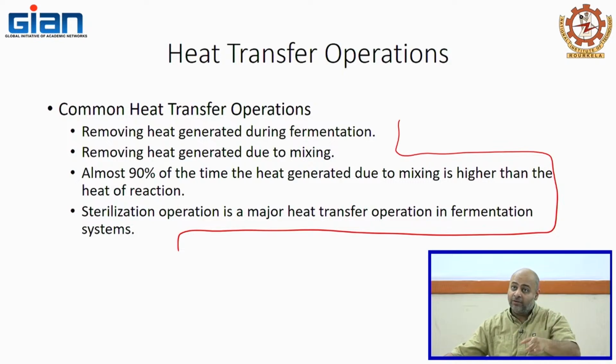Then again, it will depend on the fluid properties, the viscosity. You have to look into the table and get the values at a specific temperature: what's the viscosity of the medium, the density of the medium, and then you are going to use your Nusselt number equations to estimate the value.